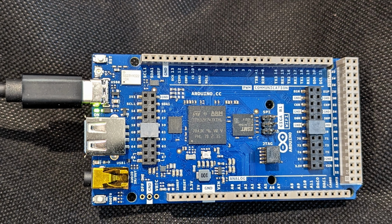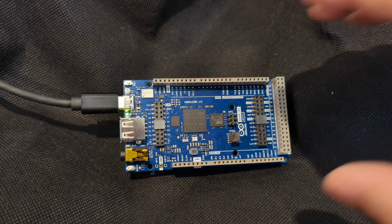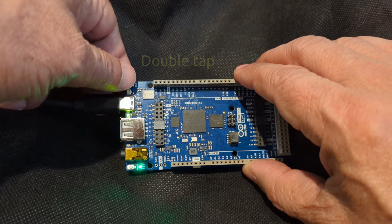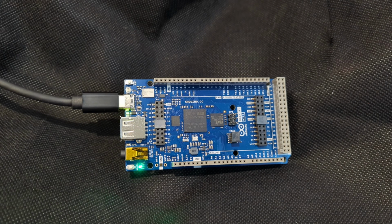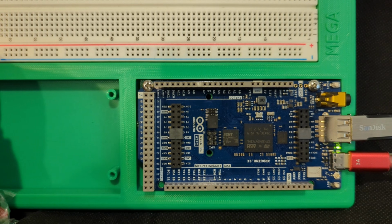Double tap the reset button in rapid succession to prepare the board for flashing. The LED light will pulse green. You are now ready to run the dfutil that was discussed previously to flash the firmware. After the dfutil has flashed the firmware, press the reset button once to enable the bootloader operation to be completed.